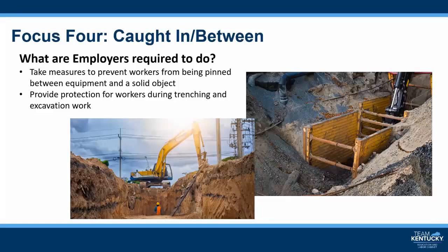They also are required to provide protection for workers during trenching and excavation work. Employers are required to take measures to prevent workers from being pinned between equipment and a solid object, such as a wall or another piece of equipment, between materials being stacked or stored and a solid object, or between shoring and construction materials in a trench.